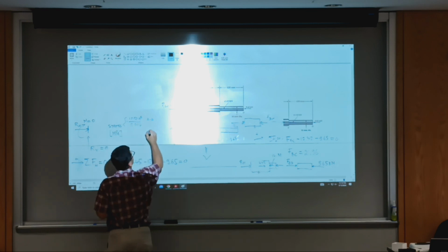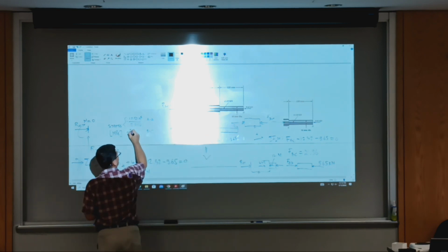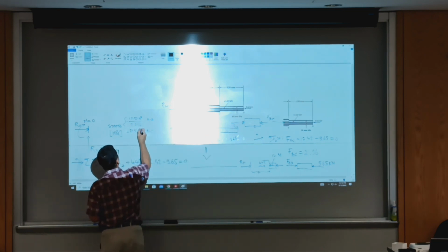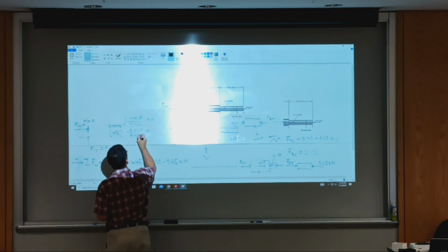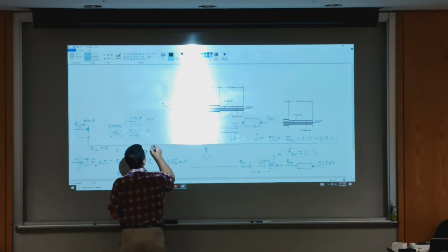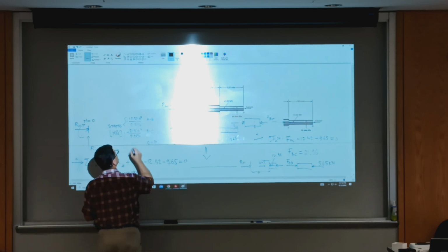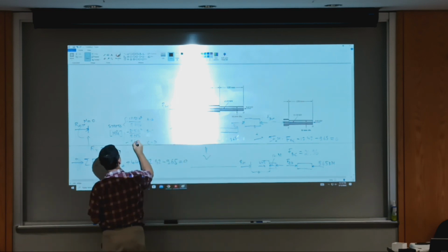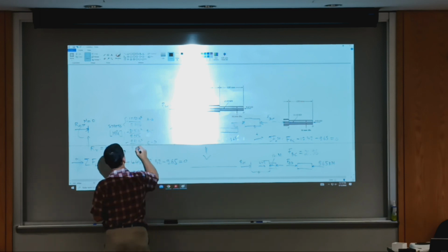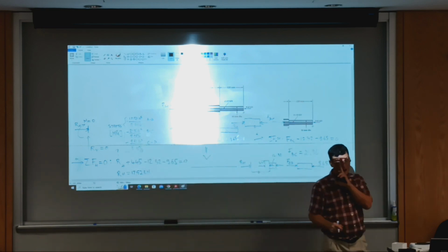And then between B and C, I have this load, negative 21.96 times 10 to the power 3 to go from kilonewtons to newtons. Diameter remains the same, pi 25 squared over 4. And then lastly, between C and D, I have the compressive load, negative 9.62 times 10 to the power 3 over pi, and the new diameter is 16 squared over 4, in megapascals. Is it clear what I did?